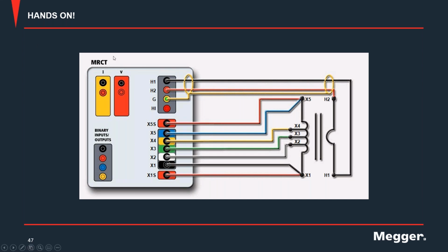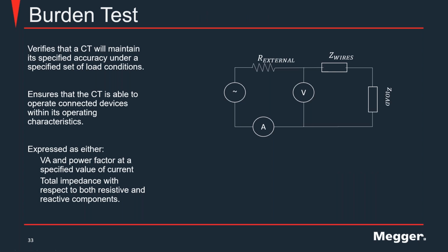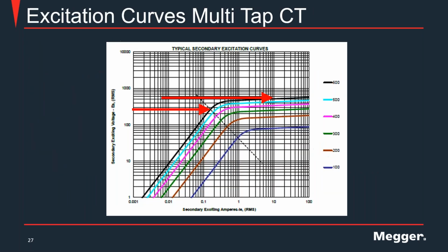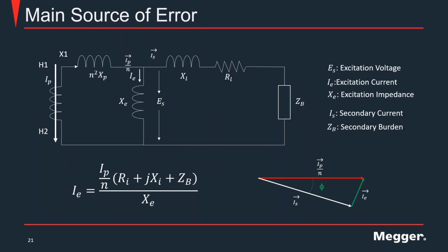Okay, both are design considerations, right? And these are indications you will find on the nameplate, depending on the CT type. ISF, meaning instrument safety factor, is for metering type CTs. Remember, when I went over the differences between the two, on metering type CTs you don't expect large faults in the system.